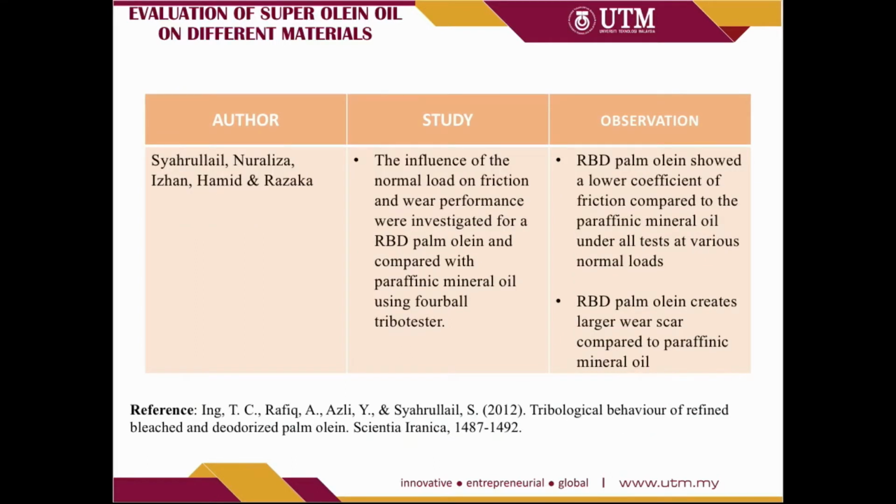A study conducted by Shahrulail, Nuraliza, Izhan Hamid and Razaka investigated the influence of the normal load on friction and wear performance for RBD palm oil, compared with paraffinic mineral oil using a 4-ball tribo tester. They observed that the RBD palm oil showed a lower coefficient of friction compared to the paraffinic mineral oil under all tests at various normal loads, but it created a larger wear scar.